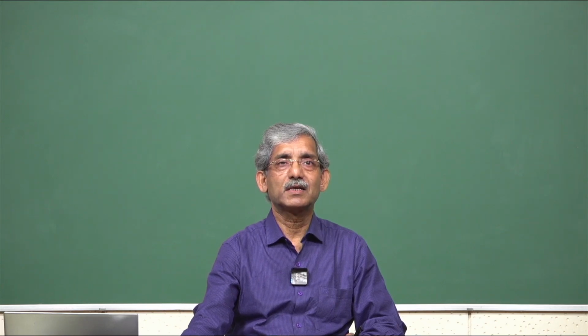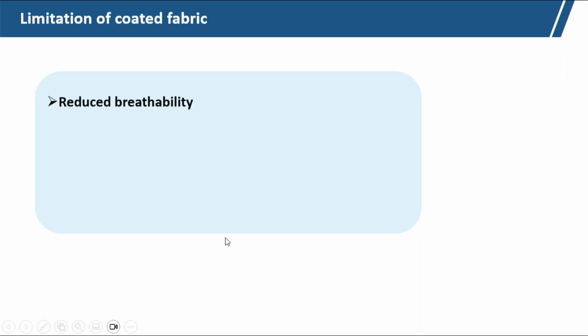The limitations: it reduces the breathability, but in laminated fabric, as pores are available, breathability is not affected. Here it reduces the breathability, and it has less flexibility and is stiffer because of the coating and the solidification of the coating material, the polymer.